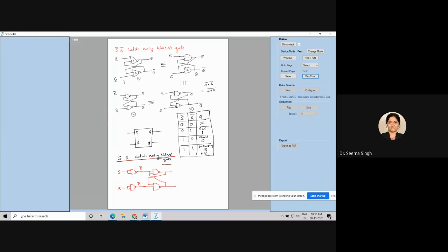And all of you, please remember, a 2-input NAND gate, when feedback comes, it goes as the input of NAND. I have seen many students connecting it to this one wire only. It is a 2-input NAND gate, so it should go as the input of this NAND gate.